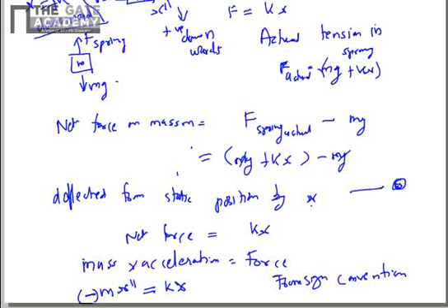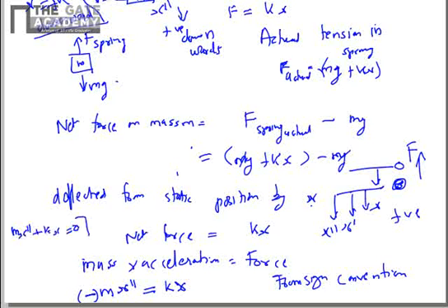So you have the zero position here. This is x, x dash, x double dash. This is the positive side towards the bottom. In the present case the force is towards the top, because the displacement is from the zero position towards the bottom, hence x is positive, but x double dash is towards the top, hence it is negative. From this we get our equation of free vibration, that is m x double dash plus kx is equal to 0. So we will go about solving this equation in the next slide.